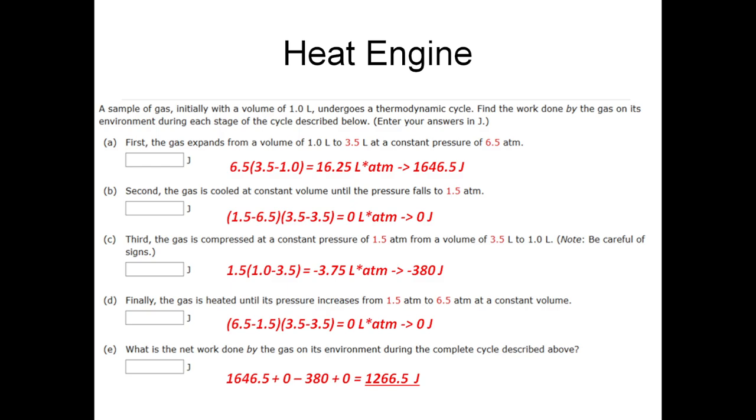We're increasing the pressure, probably by heating the gas. We are heating the gas up, increasing the internal pressure, but its volume isn't changing yet, so no work done in or out. Another answer of 0. It'll only do work again once it's allowed to expand again. And so all of these steps exist in a cycle. Extend, then there's 3 steps needed to contract it again, then it's ready to extend again.